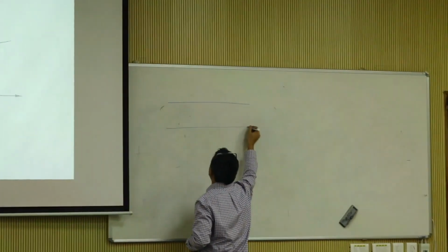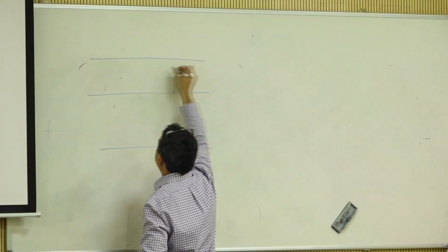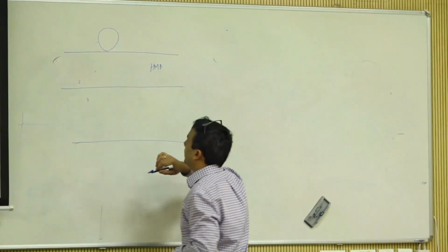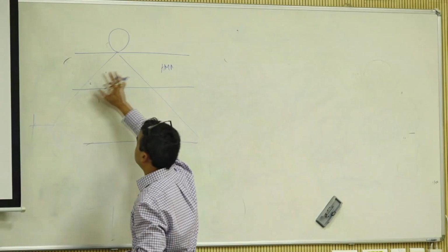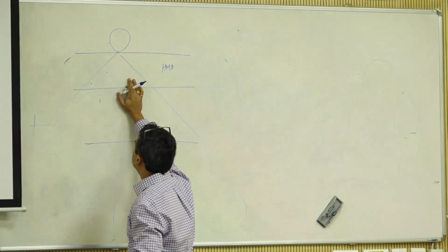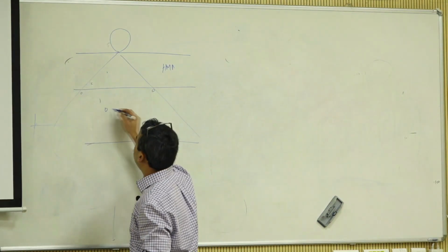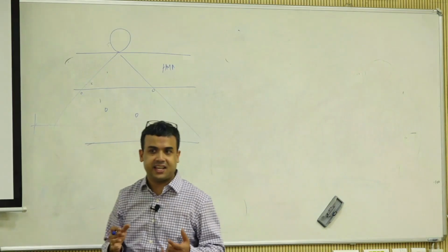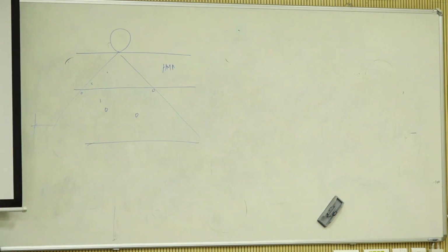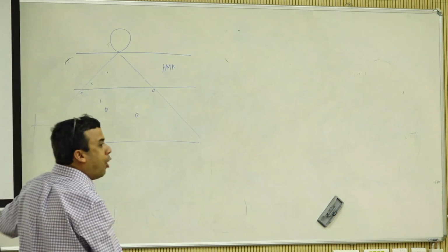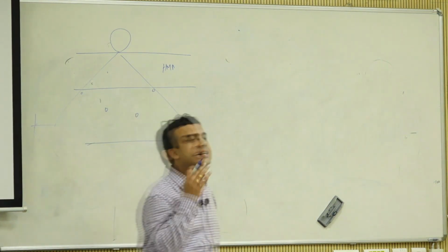In your traditional pavement design, let us say this is your HMA and this is your load, right? And then the stress is being dissipated like this. Yes, the slope will change at the interface, but I'm ignoring that in this case. So you know that between this point and this point, and this point and this point, the stress is different. When the stress is different, that actually means that your modulus is also different. It is a stress dependent material.